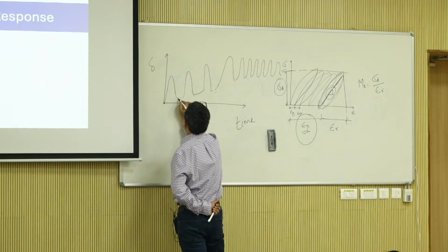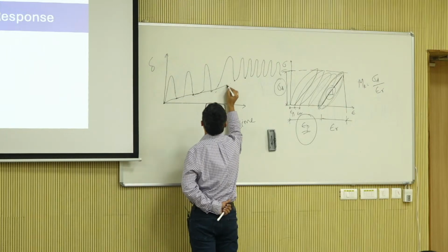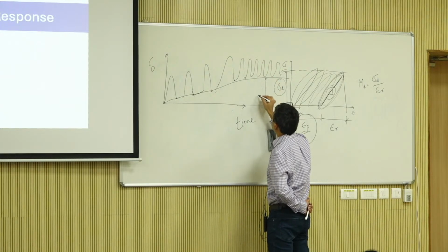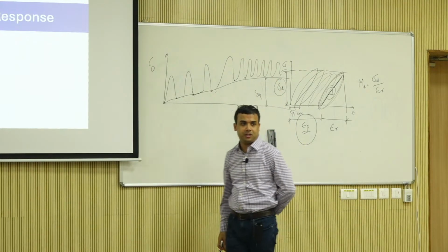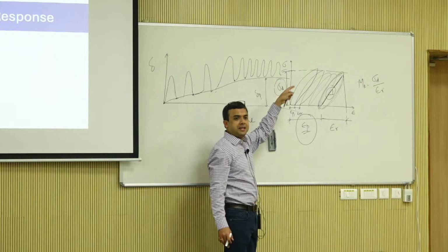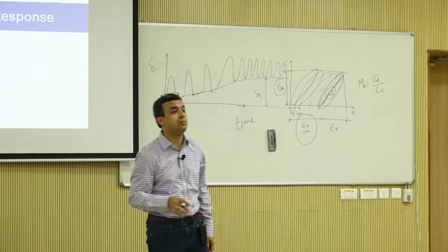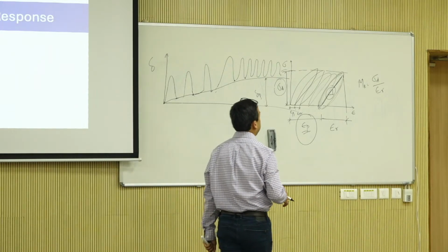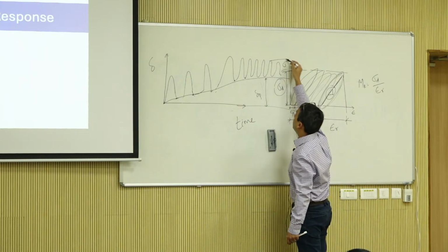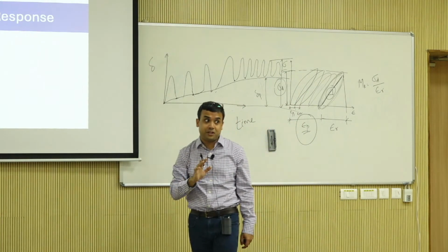Now if you take the bottom points of all of these graphs and you draw this, that becomes your delta P, or permanent deformation, right? And everything on top is the recoverable part. So if you put an LVDT on your specimen, what are you going to measure? Deflection. The vertical, which is the total, right? You're going to measure the total.